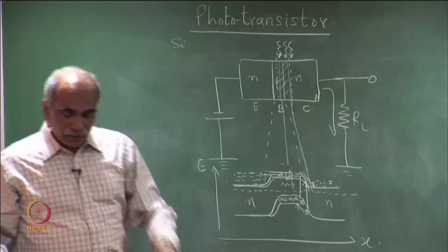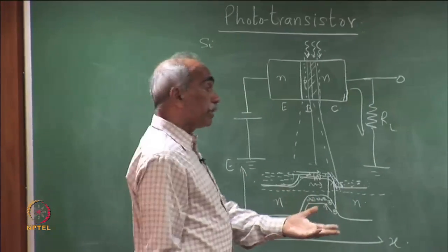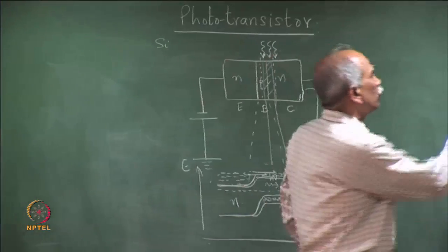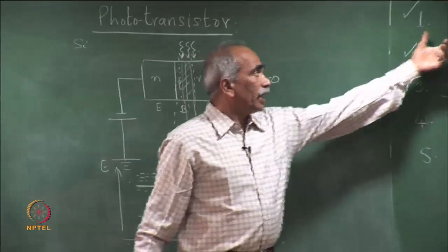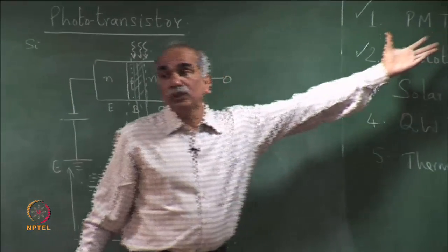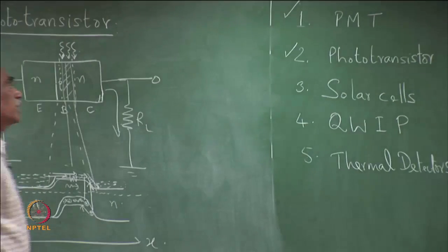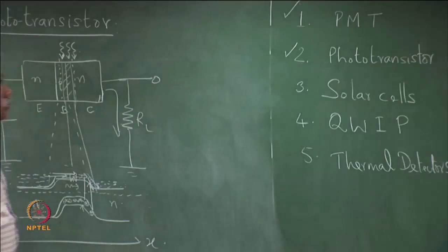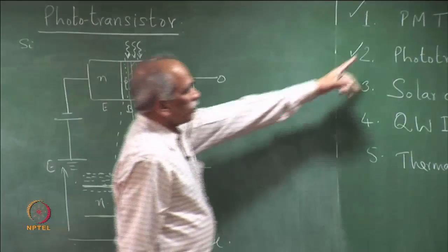So, in the last class we discussed the avalanche photodiode, which has a current gain because of the avalanche process. Exactly like that, the photomultiplier tube has a large gain, again due to the avalanche process. It is not a semiconductor PN junction diode, but works on the principle of the photoelectric effect and avalanche process.